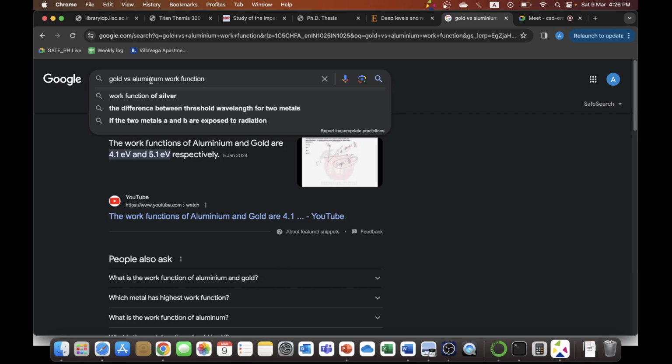Again, these two entities for this problem will not matter because these are dependent on the oxide and semiconductor, not on the metal. The metal term will come only for phi ms, and since phi ms is higher for gold silicon as compared to aluminum silicon, this term enters over here. This is essentially to arrive at the flat band. We'll come to this in the latter part of today.